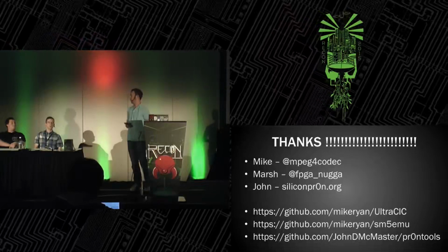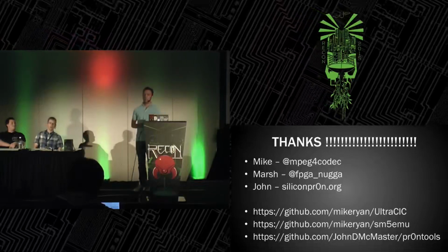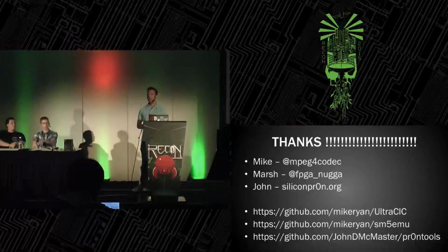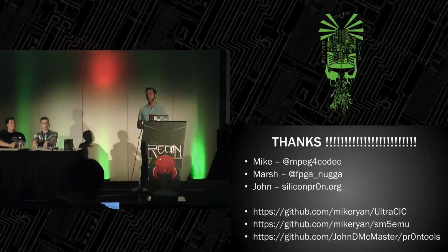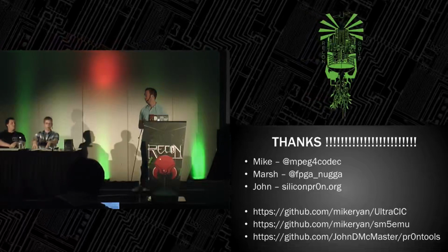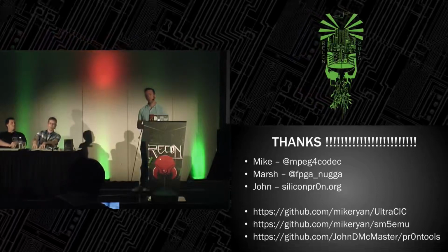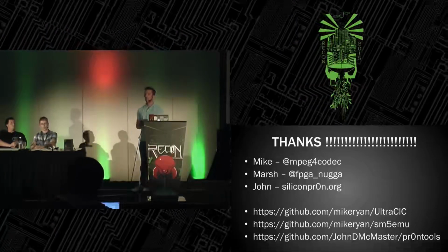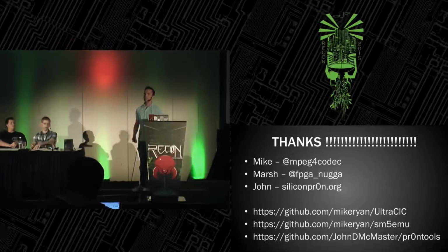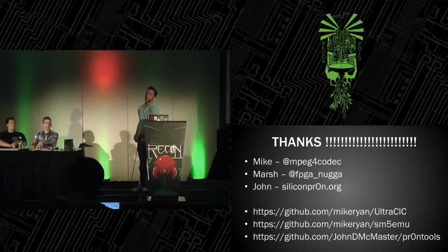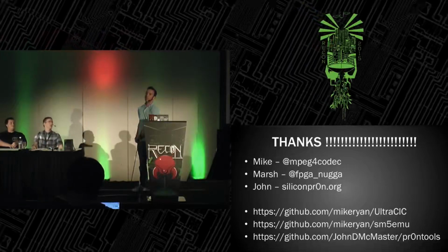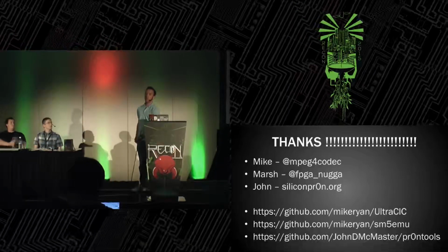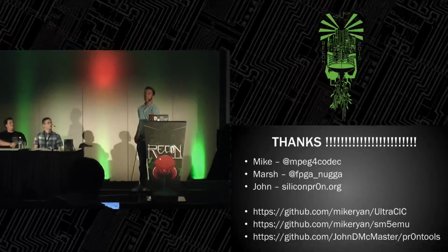Well, like I said, the PIF is what you got to worry about, and it lives inside the console. It does all the system bring up, handles all the resets and NMIs for the MIPS CPU, and polls the controllers and all that stuff. So basically, yeah, you can blow that away and replace it with your own. You'll have to lift some copyrighted bootloader code out of there, put it in your new one, and then replicate all this functionality. It's not a practical approach, but if we get the PIF code, maybe there's a hidden mode where the CIC can tell it, hey, just stop bugging me and let it run forever.